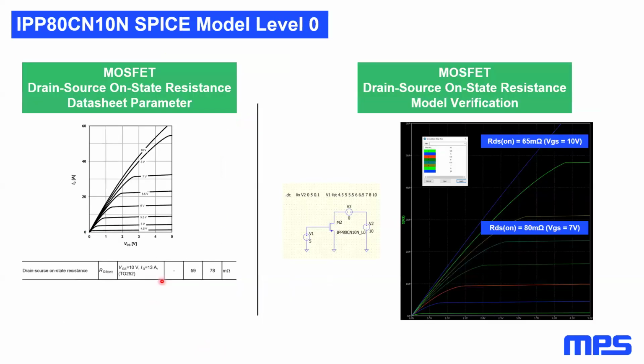One other way to estimate power dissipation is with the help of electrical circuit simulators, such as SPICE-based ones. MOSFET manufacturers usually share publicly the SPICE models of their devices, and sometimes they are found in different levels of complexity. The more complex the model, the heavier the simulation will usually be.